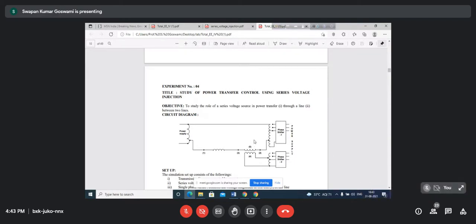There is another purpose. So what is that? Another FACTS device is called the interline power flow controller that can actually transfer power from one line to another. That means, assume that there are two parallel lines, a double circuit line. You have heard about double circuit lines. Double circuit lines are adjacent to each other. In most cases, they run on the same tower. So using the FACTS device, basically the interline power flow controller, IPFC, we can transfer power from one line to another, and that is demonstrated here again with the help of this transformer.